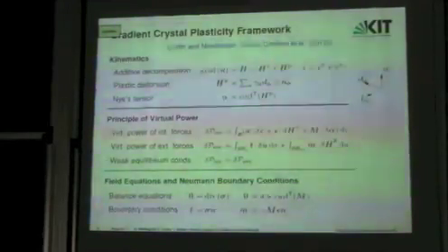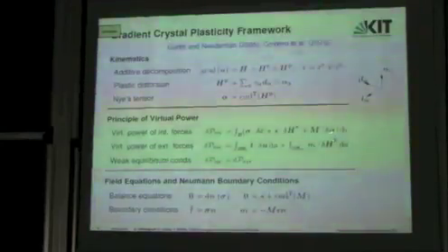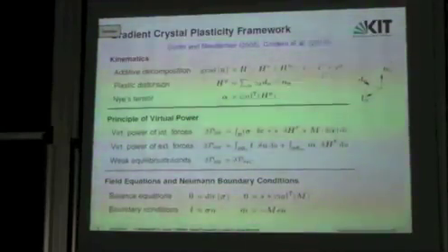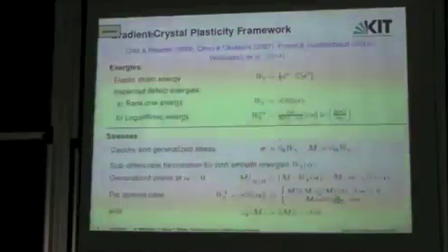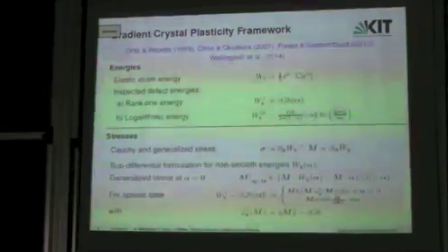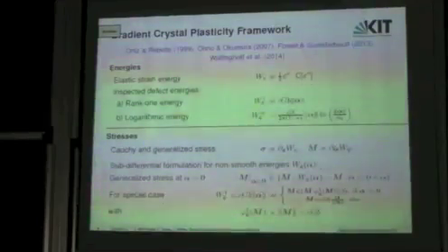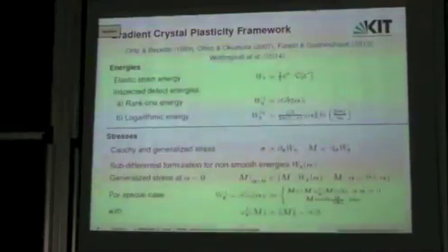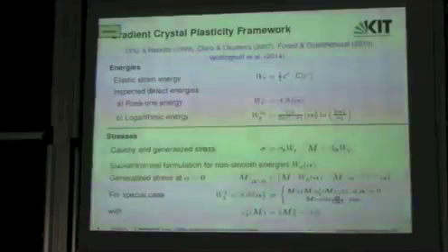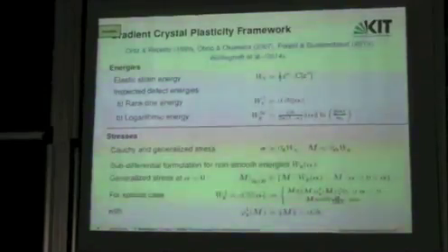Okay, in the next step you also have to say how can I compute these stresses, and therefore you need constitutive assumptions, and this is what this talk is all about. We want to investigate promising constitutive candidates which act as potentials for the stresses, and therefore the classical energy which is given here is extended by a defect energy. And this defect energy depends on the dislocation density tensor,